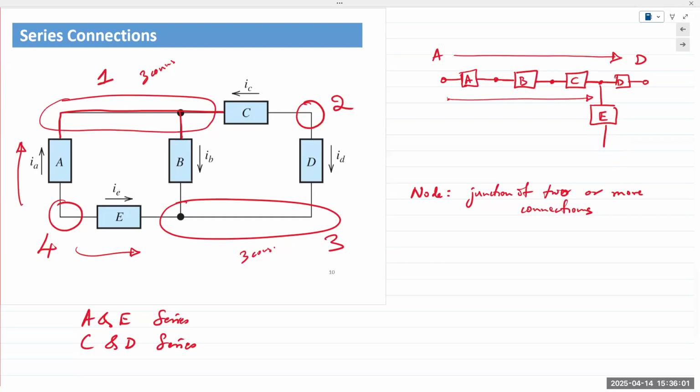So as a visual illustration, let's say I have a voltage source, connect a resistor, and then I have another resistor. We'd say that those two resistors are in series, right? Because they only have one connection right there. So the resistors are in series. And at the same connection, if I now connect a third resistor, by its first definition, we would say that they are no longer in series.